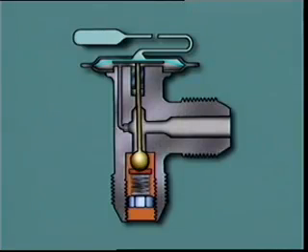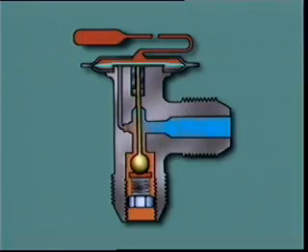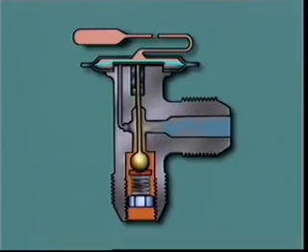Higher temperatures will give higher pressures, and this will tend to open the valve wider and allow more refrigerant to flow through. Lower temperatures will give lower pressures. This will tend to close the valve and reduce the flow of refrigerant.